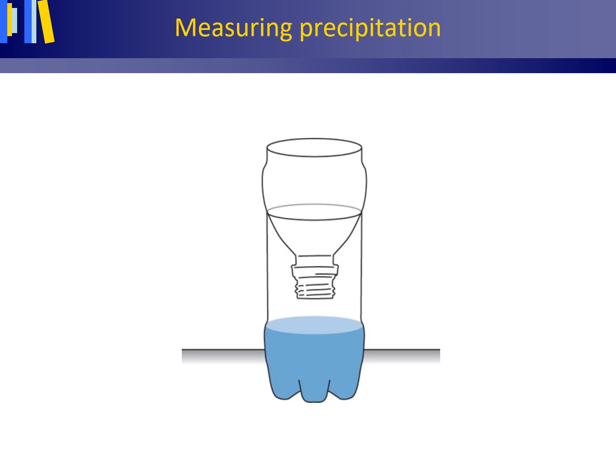flat impermeable surface after rainfall. A low-budget way to make a simple collector-type non-recording rain gauge for measuring the rainfall depth is to buy a plastic bottle in a shop, drink or dispose of the bottle's contents, cut the top from the bottle at about 2/3 of the height of the bottle, turn the top around and attach the turned over top to the lower 2/3 of the bottle, as shown in this figure.